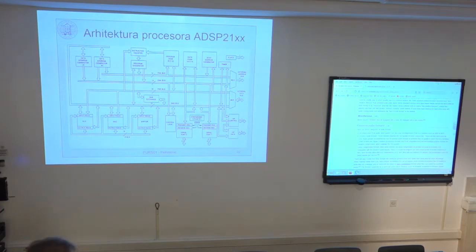So if you don't have some kind of large data array that must be processed in parallel independently for each of the units, then you have the bottleneck, because you cannot get all of this data simultaneously. But if the data is locally stored in the registers, and if these 16 registers are sufficient to enable implementation of this algorithm, then it's okay. Then all of these units can work in parallel. Okay.